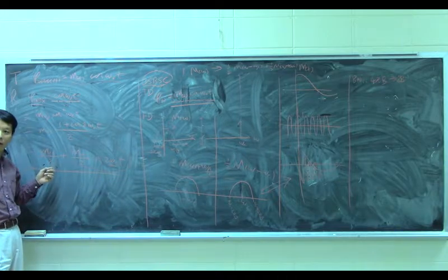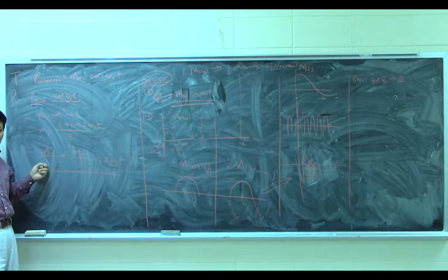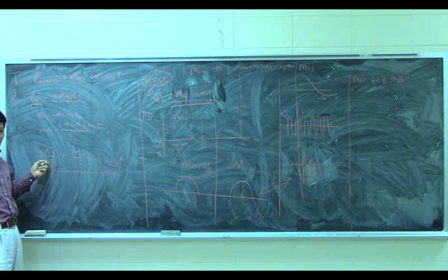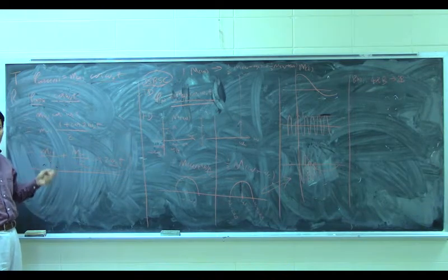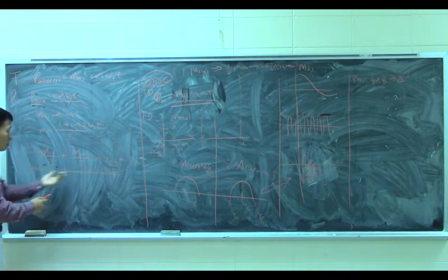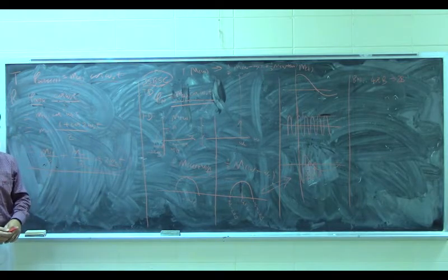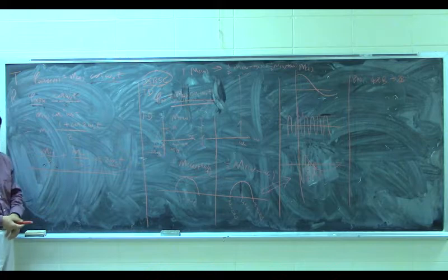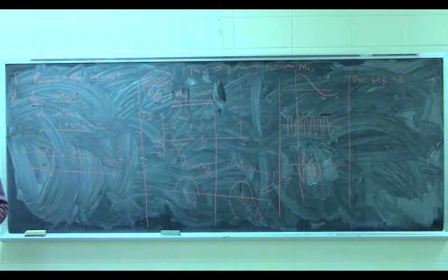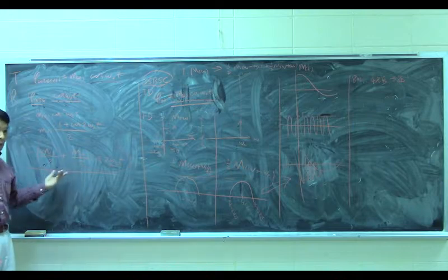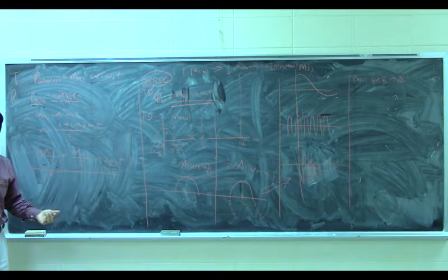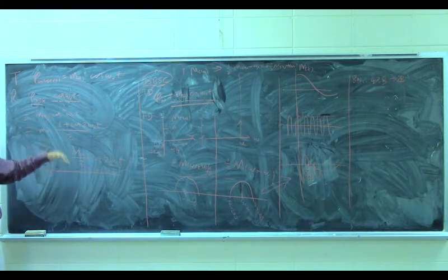How about this one? Oh, this one is good. This one is our baseband signal. That is what we want. So if there is any way that we can separate these two, because in time these two are combined together, right? If we can separate these two, then we are done. This is what we want. So how to separate these two? Divide. This is the process of demodulating.